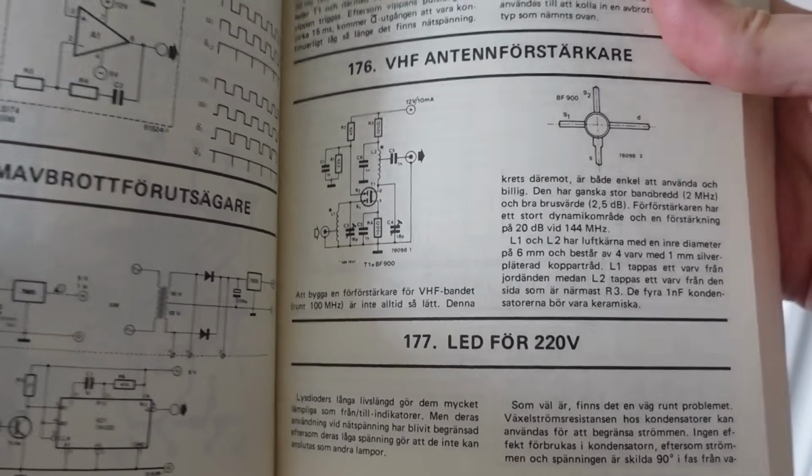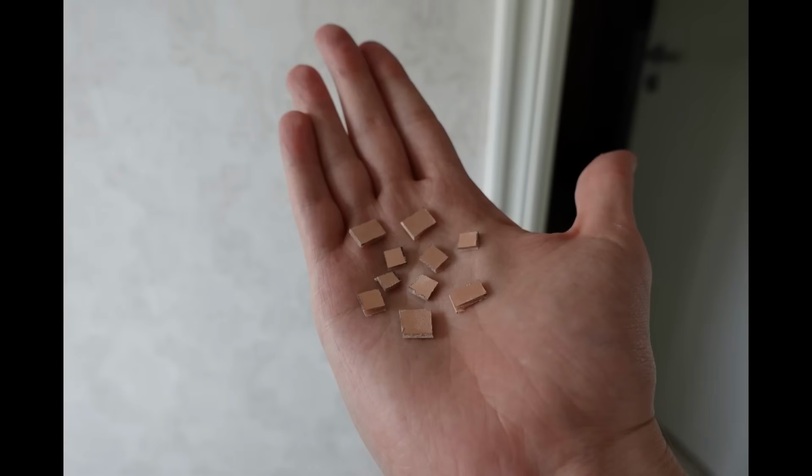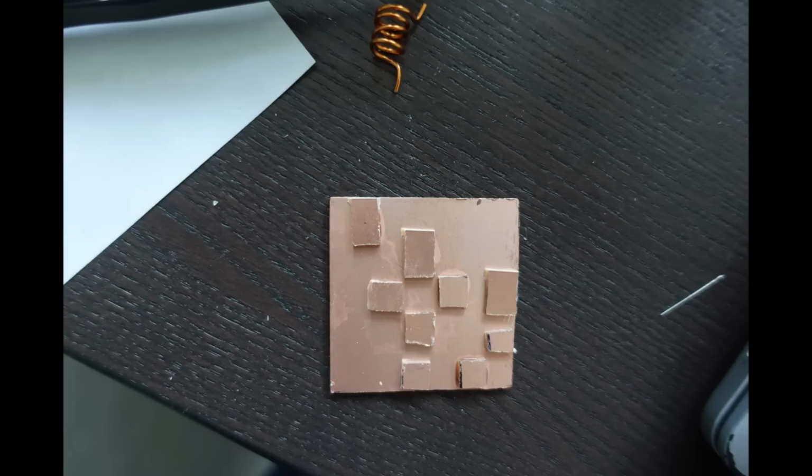And for this one, I'll use yet another construction technique. I'll build it Manhattan style, which at least was pretty popular in ham radio circles. I start off with a blank piece of copper clad. I then cut out a bunch of these little squares of the same material. I then glue these onto the board to create islands. The baseboard is my ground plane, with no interruptions. The islands are where the other signals go.